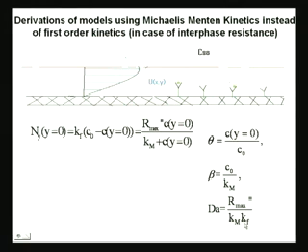This is something new, and we have not defined the Damkohler number in this way previously. Why? Because we never handled a nonlinear reaction before. This is the first time we handle a nonlinear reaction, and so we come up with this set of variables. You might ask how you come up with these variables at this point. Theta is very straightforward, but these two variables are not as straightforward. Once I recast the equation in dimensionless form, you will start to see why I do that. So, now see this.